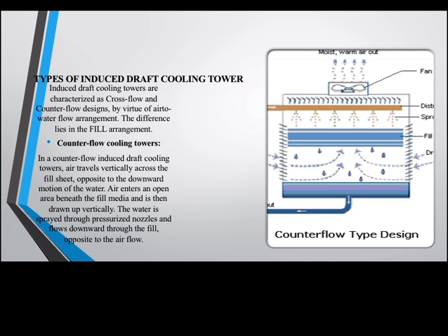We have types of induced draft cooling towers. The induced draft cooling towers are characterized as cross-flow and counter-flow designs by virtue of air-to-water flow arrangement. So the difference lies in the fill arrangement. So we have the fill arrangement over here.